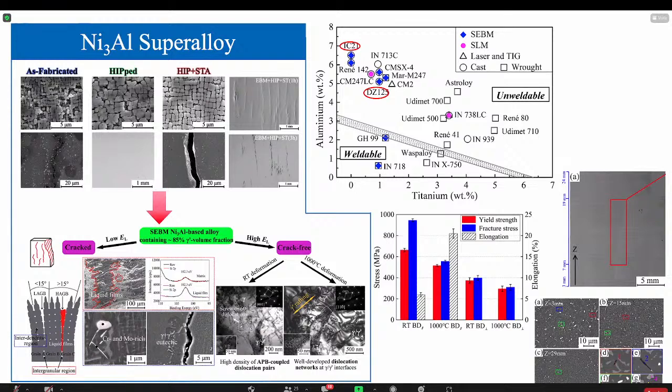However, our future work is going to focus on the microstructure degradation, because for this high temperature powder bed, when we build these high gamma prime nickel-based superalloys, when we finish the building, and you look from the bottom to the top in terms of the microstructure, you can also see this TCP phase.